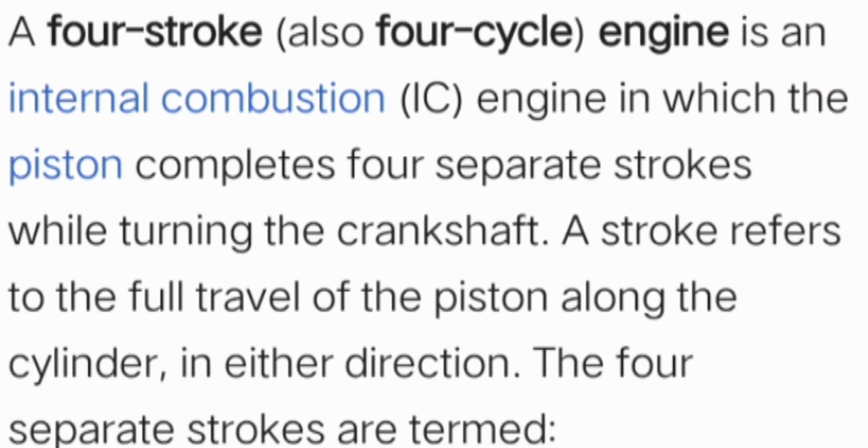A four-stroke or four-cycle engine is an internal combustion engine in which the piston completes four strokes while turning the crankshaft. A stroke is the travel of the piston along the cylinder in one direction. The four separate strokes are termed intake, compression, power, and exhaust.